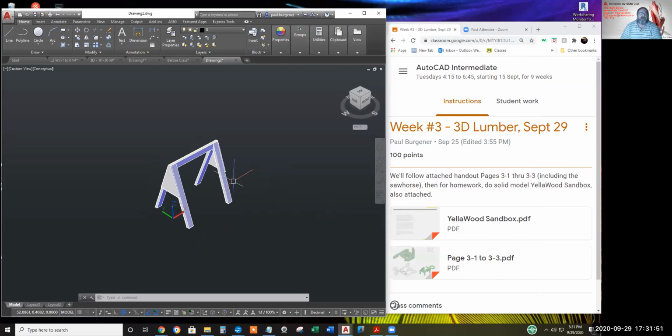Well, I have made the assumption that an AutoCAD unit is an inch. Okay. And you said divide by 12. I believe you were thinking an AutoCAD unit represents a foot. Yes, you hit it on the head.